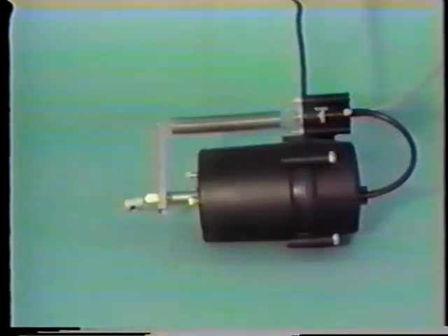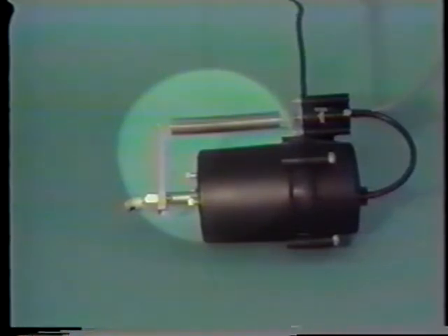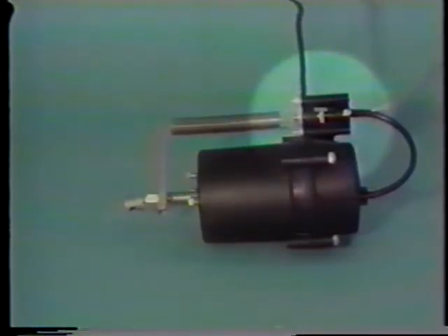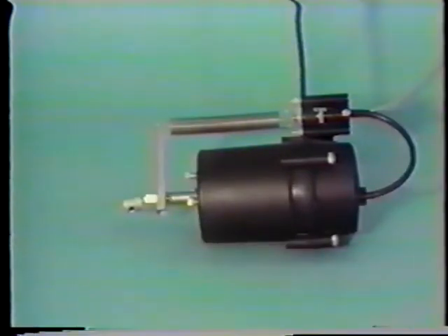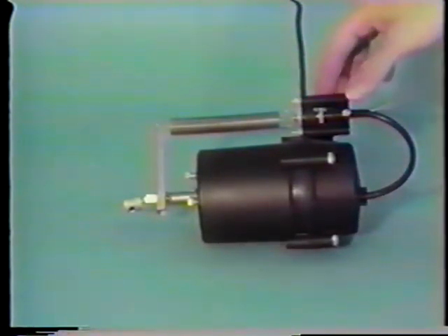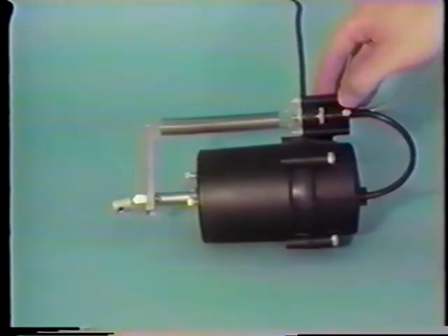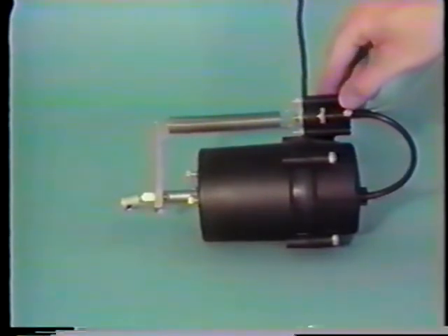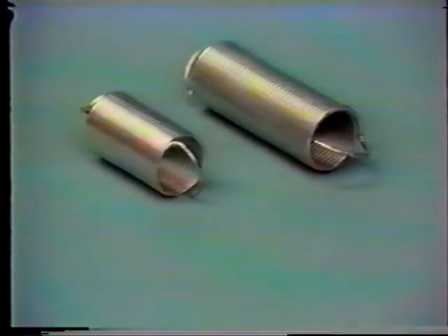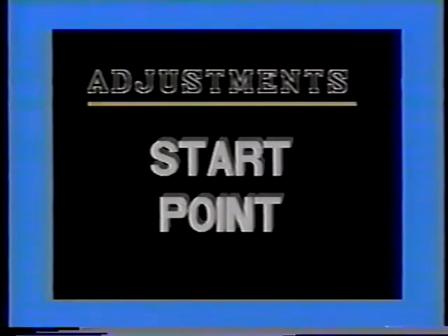The positioner utilizes a main air supply along with the signal input from the controller. A feedback arm and spring connect the actuator shaft to the positive positioner, linking movement to the input signal. The start point of the actuator is adjustable at the positioner. The stroke of the actuator occurs over a 5 or 10 PSIG span, depending upon the feedback spring utilized. The ability to adjust the start point of the actuator provides the ability to fine-tune the resulting damper action to fit the desired control sequence.